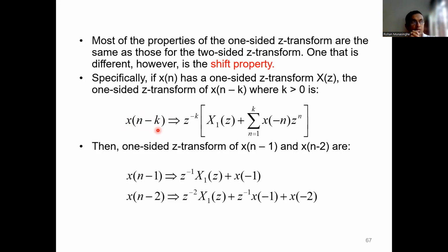All right. So if you have the original z-transform, how can you calculate the z-transform of the shifted sequence? This is how you do that. z to the minus k within brackets, X(z), and you can forget about this one if you want.